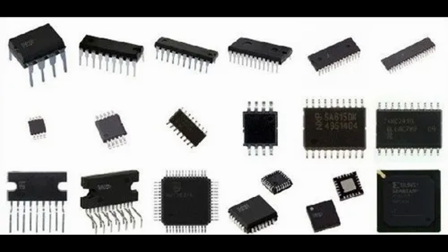These operations include: AND operation. The result is 1 only if both inputs are 1. Symbolically, it is represented as A AND B, or simply AB. OR operation. The result is 1 if at least one input is 1. Symbolically, it is represented as A OR B, or simply A plus B. NOT operation. The result is the opposite of the input. Symbolically, it is represented as NOT A, or simply A with a bar.